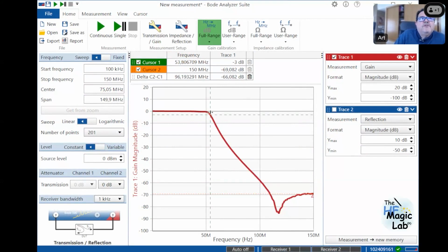So in this way, you can understand how the filter is working. The frequencies below approximately 50 megahertz are not attenuated, and the frequencies above are attenuated by some specific decibels. Remember, this is in a 50 ohms system. So when we introduce this filter in a wireless communication system where the first module is a 50 ohms source and the next module is a 50 ohms load, the system will be working exactly like you are seeing here.